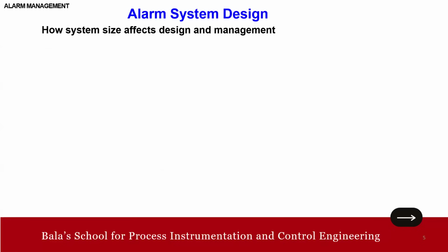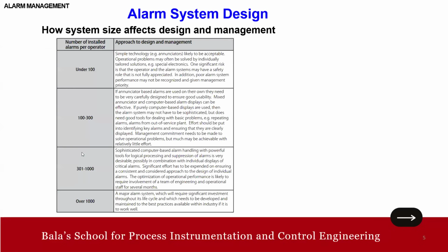The next one is very important and interesting. How the system size affects the design and management. Okay, for example, take the case here. If your number of installed alarms per operator is under 100, then the approach is simple technology, like you have to have an annunciator, likely to be acceptable, right? So operational problems may often be solved by individually tailored solution. Okay, so it's a small annunciator kind of thing, right?